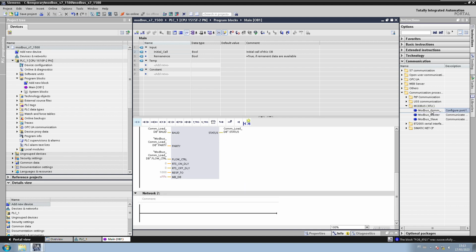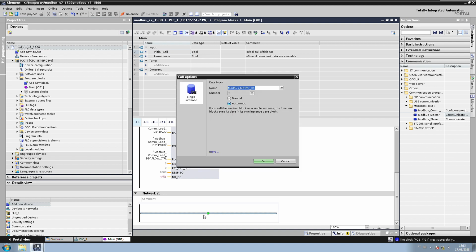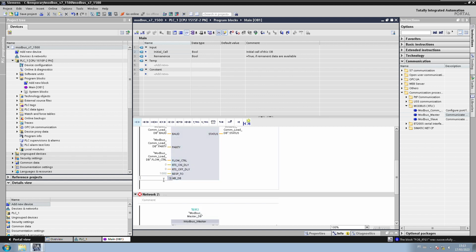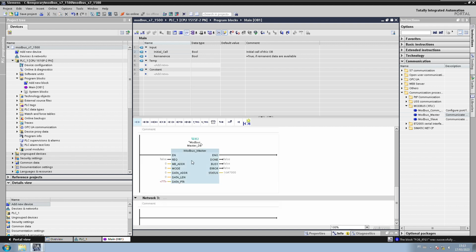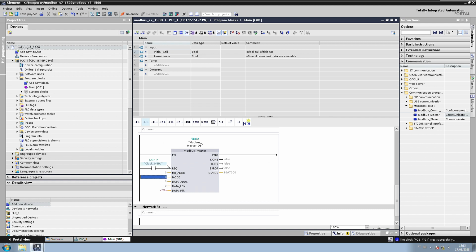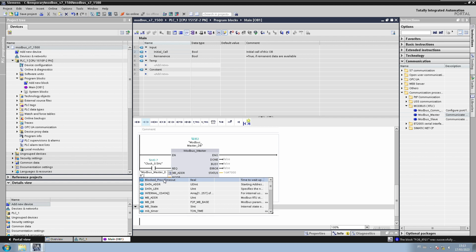And now the ModBus master block. Inside this block, it's where we do everything else later. Now I will copy and paste the block name from here to here. This basically points to the configuration block where the configuration needs to be done. Pay attention to the .mb, okay? Here, I will add a normally open contact, a trigger condition to request data from the network. Now, pointing to the block internal variables again, the exception is the last one in the bottom left, where the data that we will read will be placed.